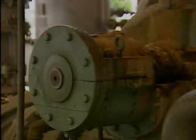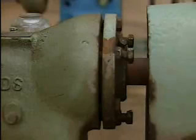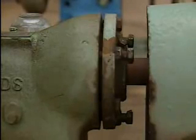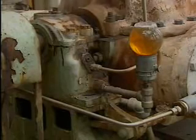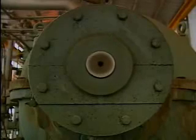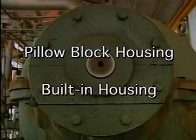Bearings are usually enclosed in housings. The housing is the part that surrounds a bearing and holds it in place. In order to support the bearing, the housing must be able to handle the types of load that the bearing is subjected to. The load is usually transferred from the shaft to the bearing to the housing. Most housings contain lubricant for the bearing, and they also prevent dirt and other contaminants from getting into the bearing. Bearing housings are divided into two types: pillow block housings and built-in housings.